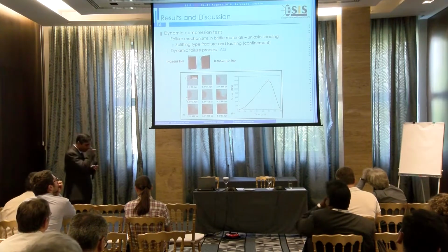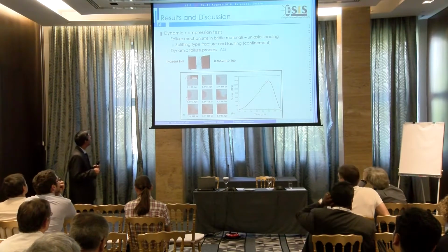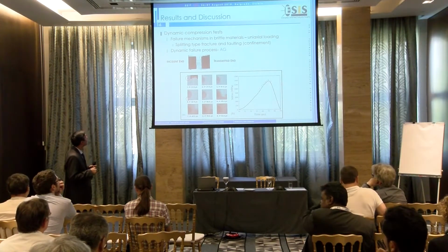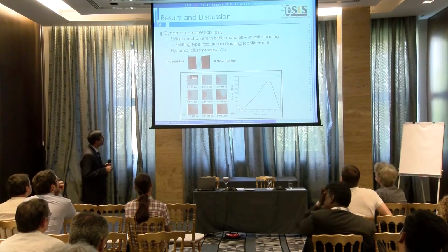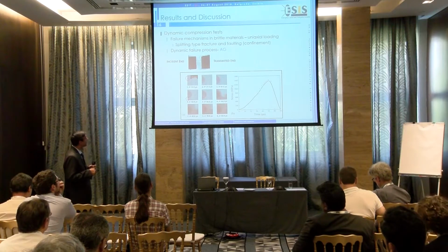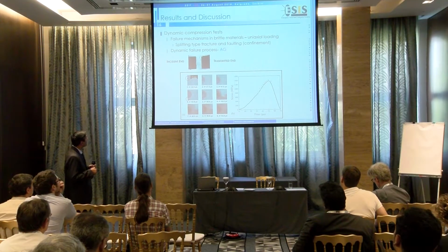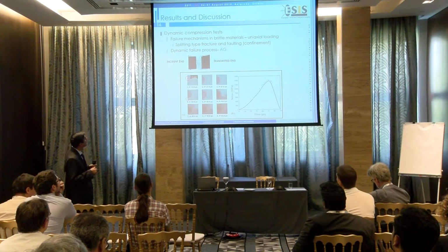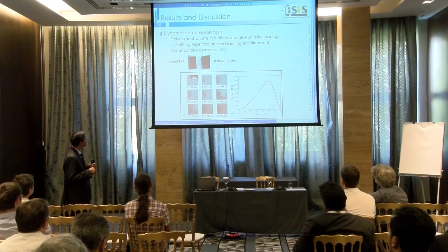Another important aspect is we have used high-speed imagery to see the dynamic damage initiation and propagation in both materials. So the 9 numbered points on the stress time curves are synchronized with the high-speed images which we captured during the testing. We can see that at 33.6 microseconds, the dark points appear, because we have used the testing technique in shadowgraph mode. Initially, when there is no damage or crack, it's bright. As some damage or crack starts to appear, the region becomes dark.